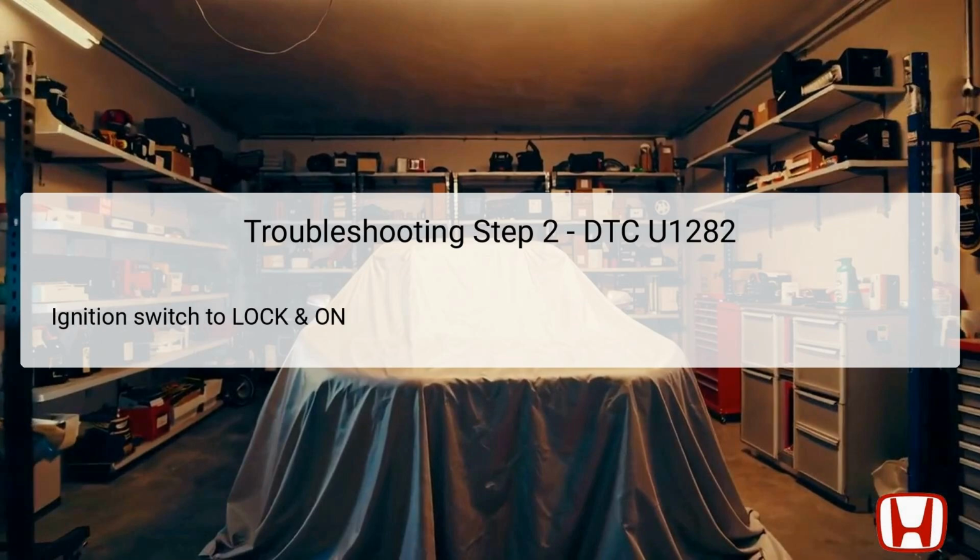After clearing the DTCs, the next troubleshooting step involves turning the ignition switch to the lock 0 position and then back to the on 2 position. This process reinitializes the vehicle's electronic systems and prompts the onboard computer to perform necessary checks. It is essential in ensuring that all systems are powered up and that any live connections are re-established.